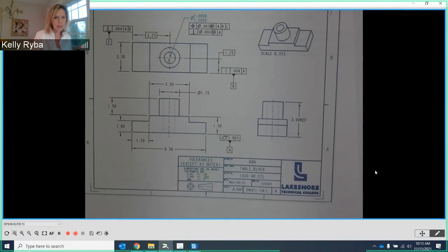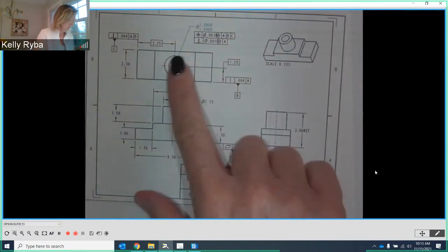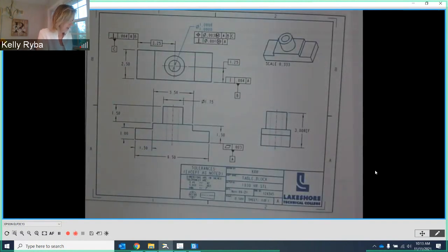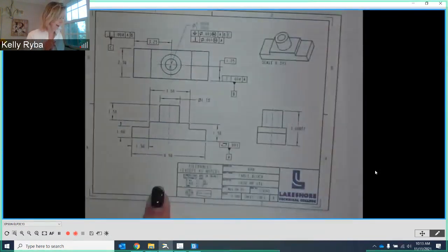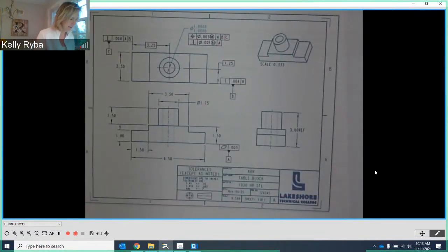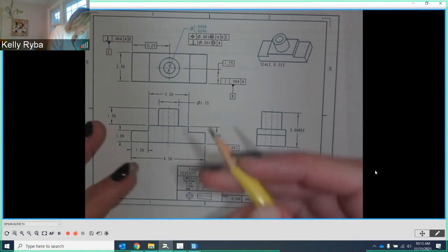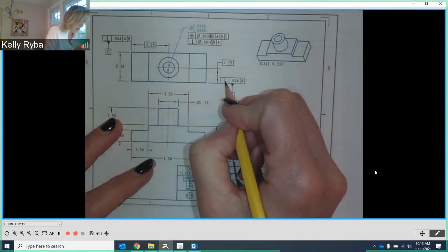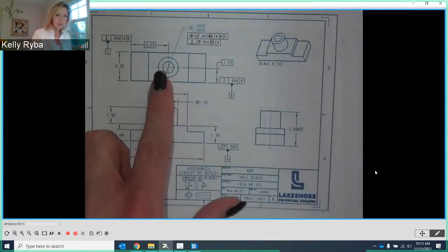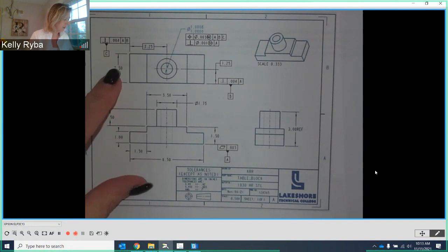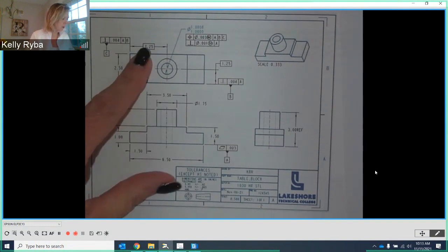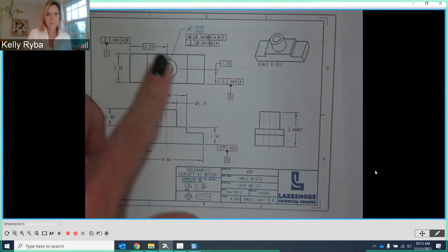So in the top view, I am going to be adding this should be a perpendicularity. I'm sure it was. It maybe on my printer. I know I'm getting a little low on ink, so that might be the reason that it doesn't show as perpendicularity here. So I'm thinking probably the case. So this is going to be the view that we need on here. So I'm going to be choosing the dimensions that are 2.5, 3 1/4, 1 1/4, and then the 1 inch diameter hole